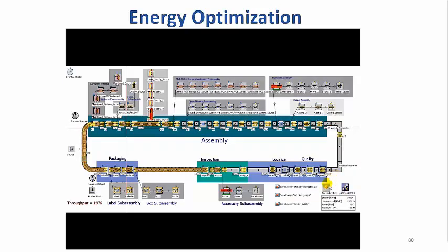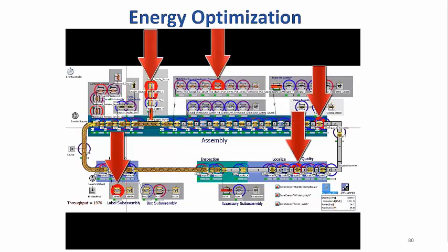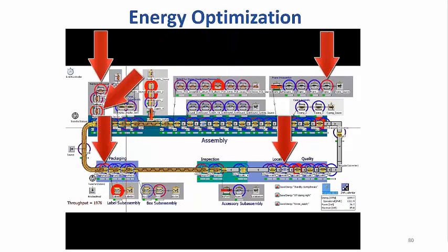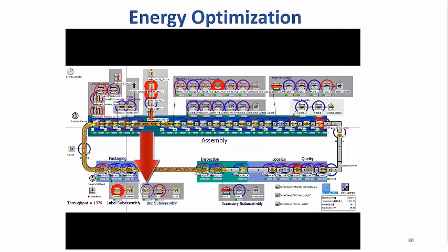Let's take a look at the Energy Analyzer's Show Visualization option. The stations surrounded by solid red circles are the ones that consume the most energy. Hollow red circles indicate the next largest energy consumers. Blue indicates the least energy consumers, and purple is in between. This visualization lets you quickly identify areas where you may want to focus on making potential individual energy improvements. This is similar to using PlantSim's Bottleneck Analyzer to help you to identify the main throughput bottlenecks.